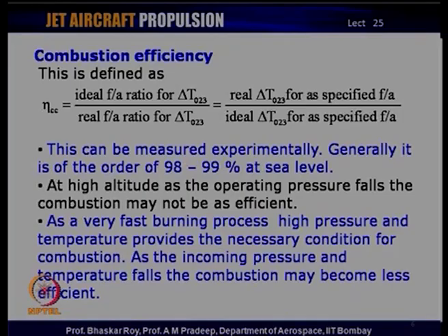Now, typically the combustion efficiencies are very high indeed, of the order of 98 to 99% under sea level operating conditions, assuming that everything has been very well taken care of. And as I mentioned earlier, you could have very high combustion efficiency and still have very high pressure losses, or you could have very low pressure losses and still have somewhat lower combustion efficiency. So, the two are not quite connected to each other.